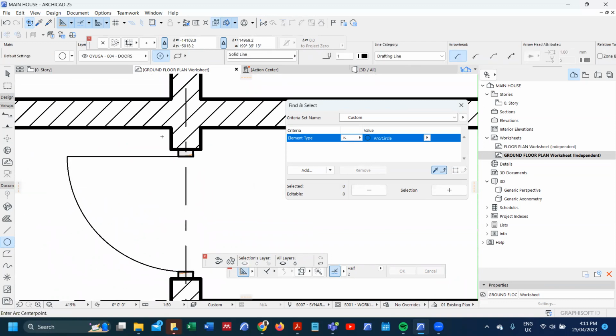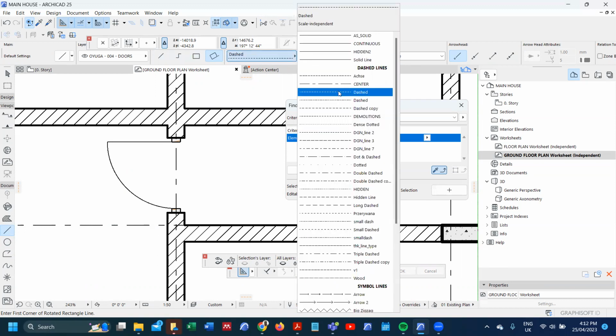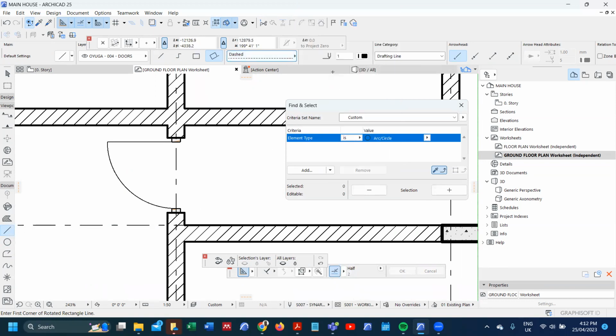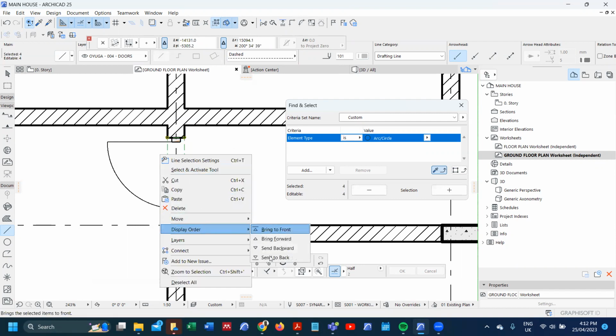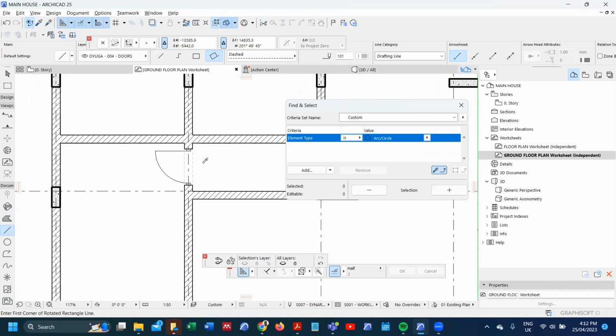The other thing that we need to remember at this level is that above the door, we normally have beams. Remember that in terms of graphical communication, you need to show things that you cannot see but are important. In this case, we have beams that are above our walls that most of the times we do not see, okay? So I can use even a lighter line so that it does not scream, does not compete with our door. So with that, I will have properly represented my door.